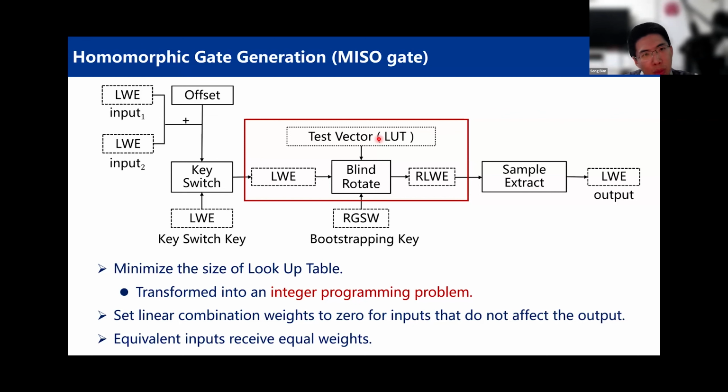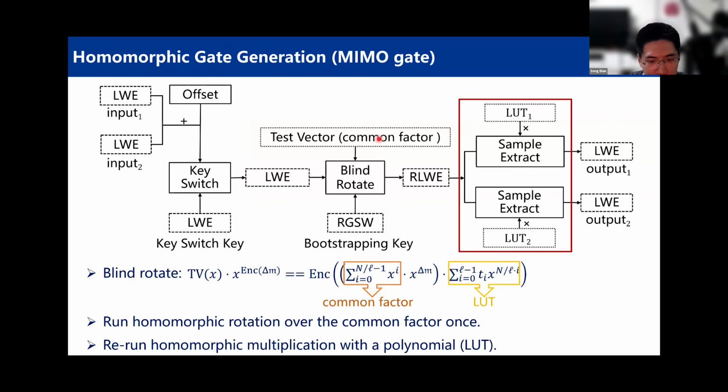The extreme case we have had is that you can evaluate a 32-input AND gate using just one blind rotation, because the AND gate is highly regular: there is only one case where you output 1, and in every other case you output 0. Those are the interesting design tricks that we can do on FHE that we couldn't do on semiconductor devices.